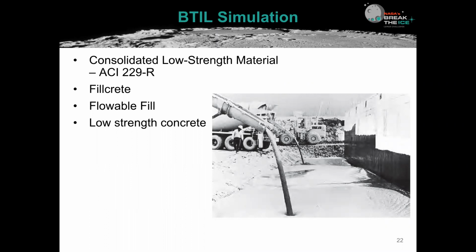When you had a large excavation and you needed to backfill it, you could backfill with granular soils, which takes a lot of labor to place properly. You have to place them in layers of, say, 6 to 12 inches, and then go in, usually in an area like this, maybe with hand tools to tamp the material down, and then place another layer. And although you're just using dirt, you're using a lot of expensive labor to do that.